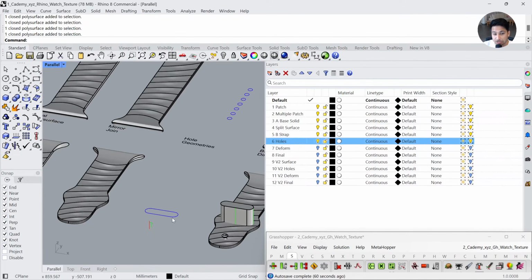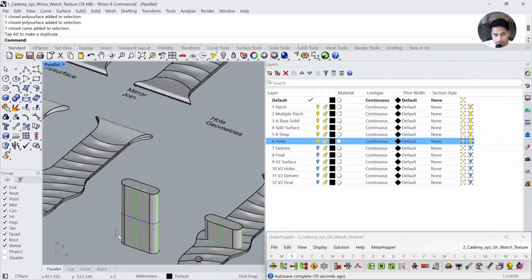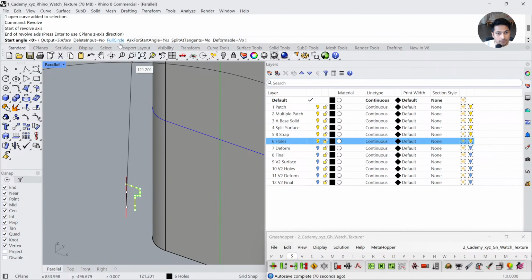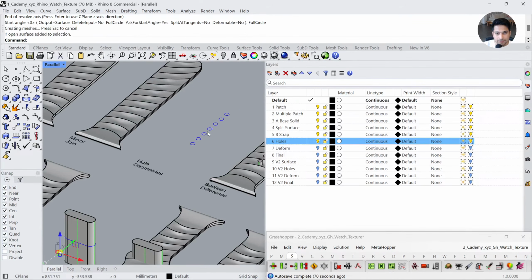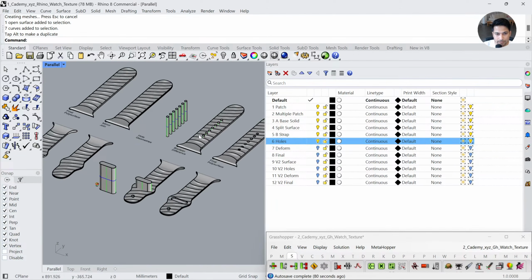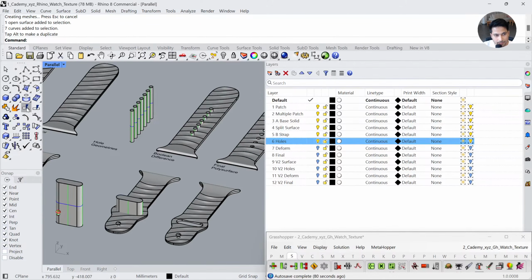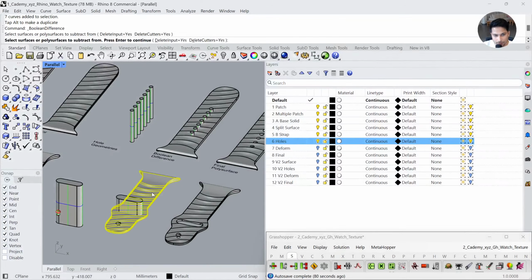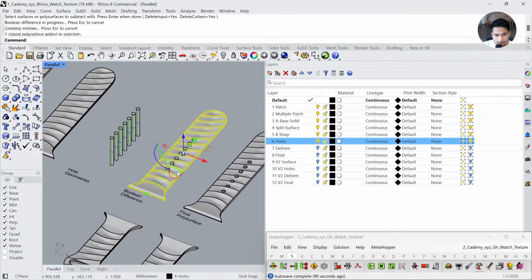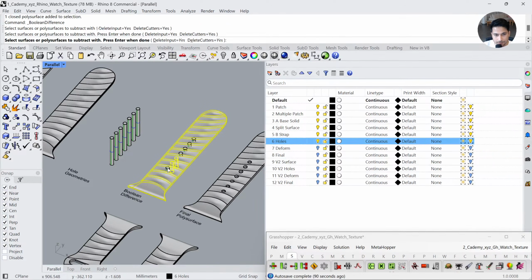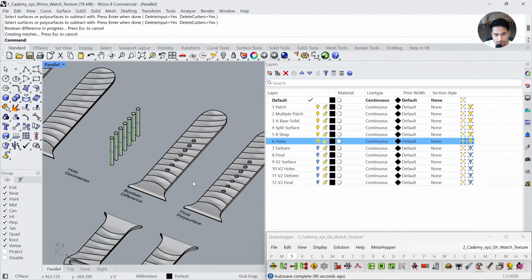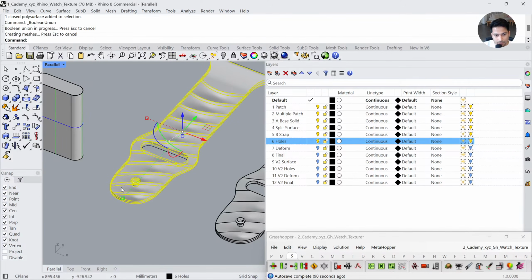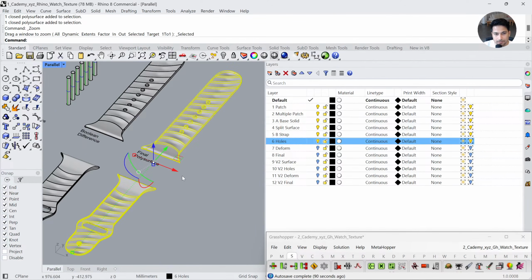I made some curves which you can then extrude. This curve which you can then revolve. And these curves which we can also extrude. So I've already overlaid them, and now you can apply Boolean difference. From here, using that. From here, using these cylinders. And lastly, you have to join them together, Boolean union. Okay, so that is the final output.